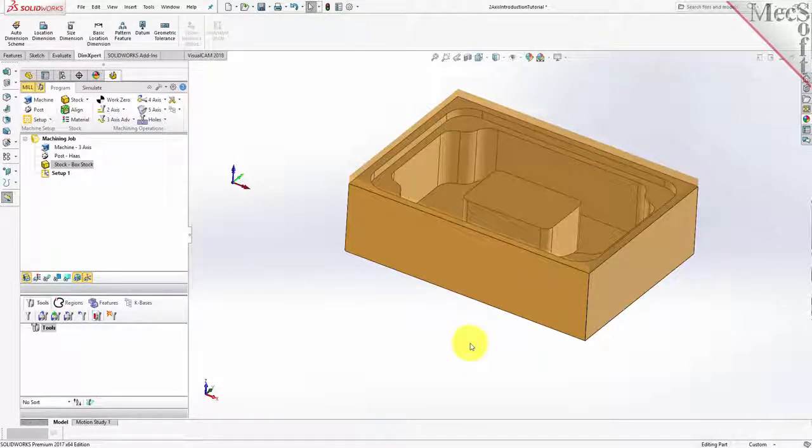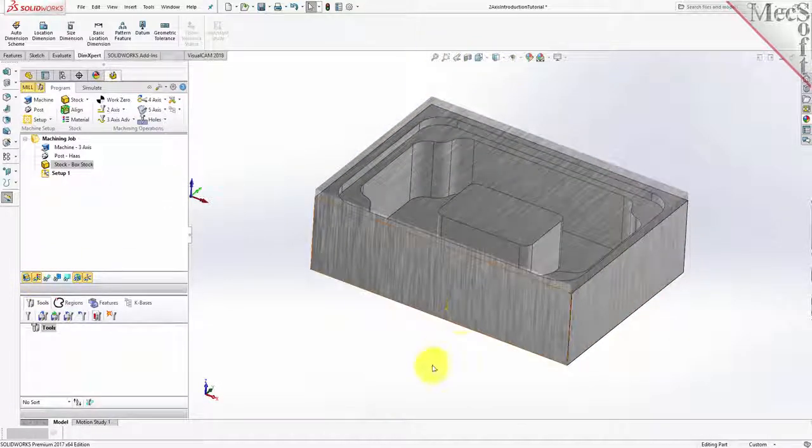If the material texture does not display on the stock, select the Material Texture Visibility icon located at the base of the machining browser. Material texture is only for display purposes, and for this part, we will leave it toggled off.